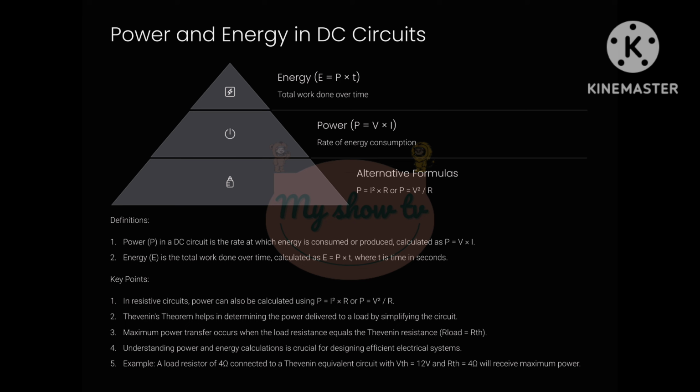Thevenin's theorem makes it easier to calculate power delivered to a load. One especially useful case is when maximum power transfer is required. This happens when the load resistance equals the Thevenin resistance. This is called the maximum power transfer condition.